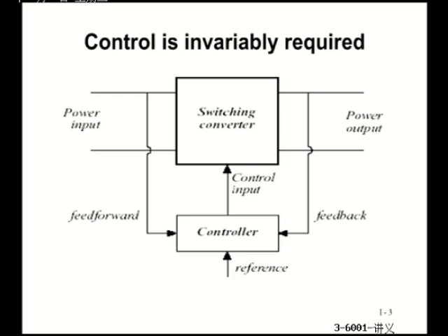Okay, and that signal is measured and sent to controller, and you adjust the controller, the adjustment is sent to the main circuit. In the main circuit, that does not affect I/O at all. Okay, then that's called feed forward, based on the signal flow diagram. So let's take a break and you think about this. Feed forward and feedback.